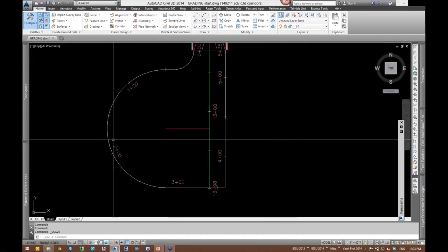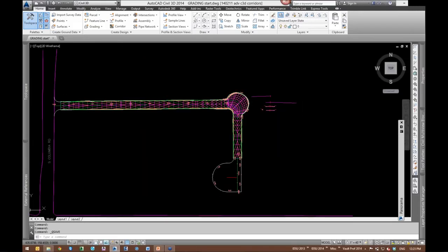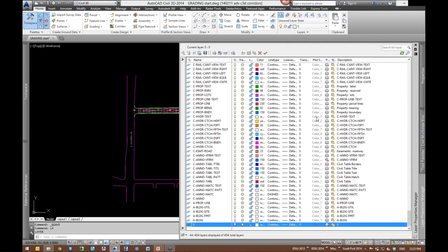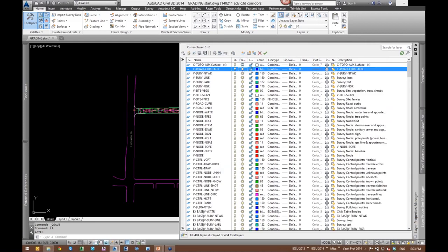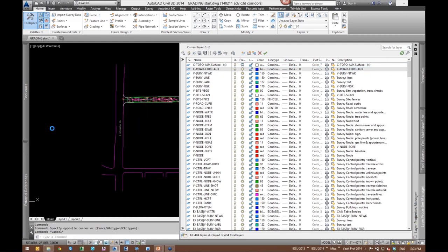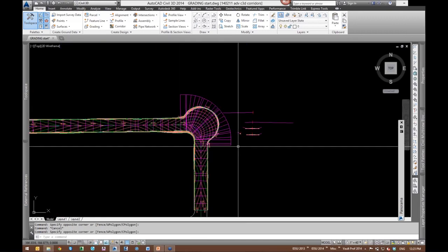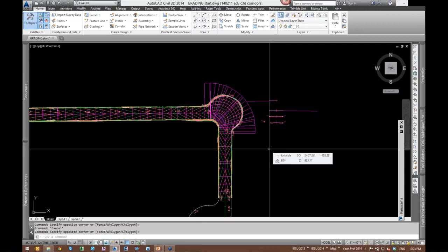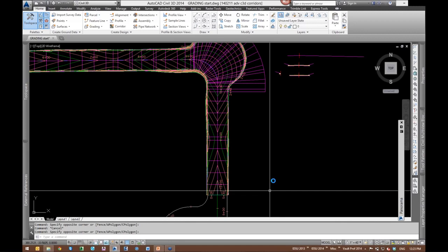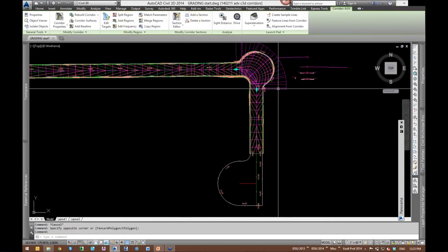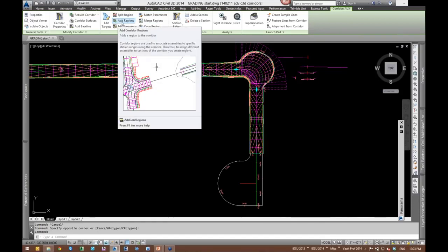So to create that drainage surface or that auxiliary corridor, we're going to turn on our auxiliary corridor again. And we're going to simply add another region to it. So it's real important, I can turn this corridor off and on. It's very important you use your object layers with the suffix wildcard to be able to allow this turning off and on. Otherwise, you've got too much going on the screen. Makes it hard to work. So we're going to pick on this corridor. We'll select Add Region. But before we do, what are we going to build this out of?